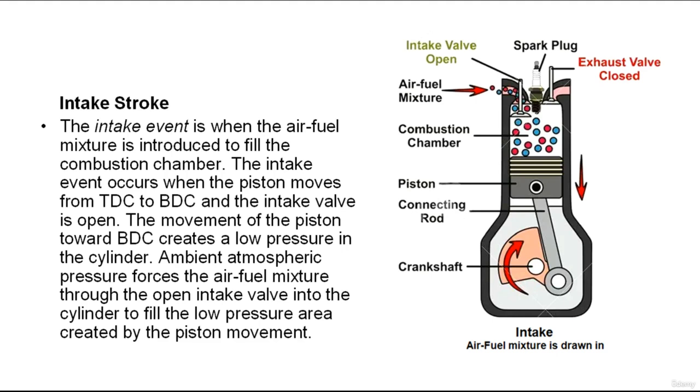So some engines are equipped with a supercharger or turbocharger that pushes more air past the valve. As the piston reaches the bottom of the stroke, the reduction in pressure stops, causing the intake of air-fuel mixture to slow down. It doesn't stop because of the weight and the movement of the air-fuel mixture.